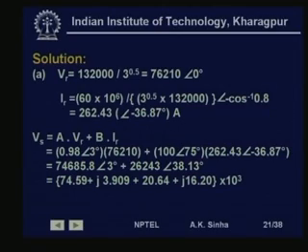When we are working with a 3-phase system, especially when we are calculating voltages and currents, it is always better to work with the phase to neutral voltages and the currents flowing in each phase. So, what we do is, first we calculate the phase voltage.